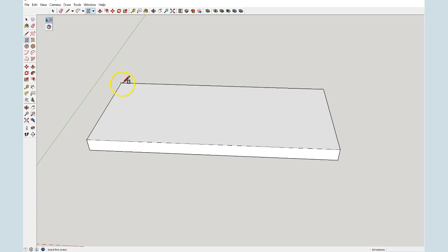So again, I'll go to my rectangle tool, and I'm going to create my legs. I'm going to make them 5 by 5 millimeters. So I'll just type 5, 5, and it'll give me my rectangles, or squares rather. Let me put one in each corner. There we go. And so now the next step is to make them actually legs.